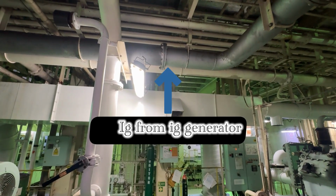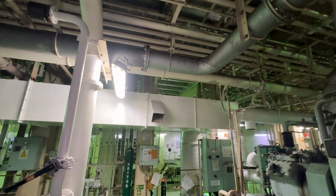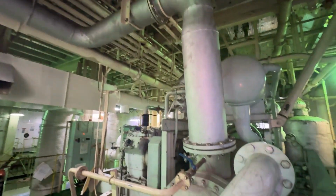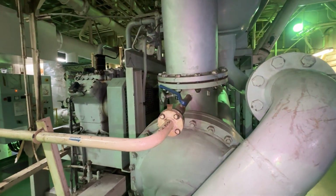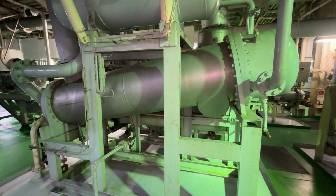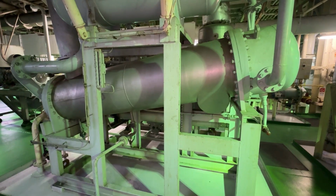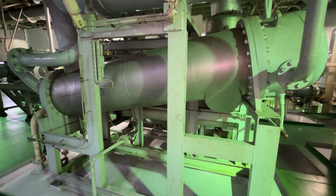So this is the pipeline in which the IG from the inert gas generator comes to the evaporator of the chiller plant. In this evaporator, heat exchange takes place in which humidity is removed from IG and warm IG becomes cold.